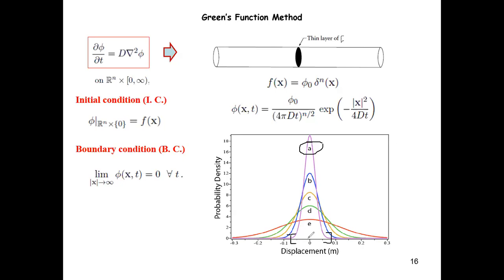Initially we have everything concentrated at this single point, and after some time, the carbon diffuses a little bit around. This is a Gaussian, so we know from statistics that the distance of this is roughly 2 sigma, where sigma is the standard deviation. Does this make sense to everyone?